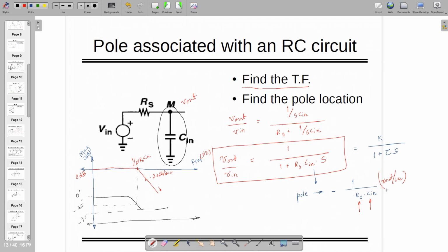So you will have one pole. And if you want to find out the one pole, you need to find out the available resistance seen in shunt with this one. Or you can say that let's change this capacitor with a known Thevenin potential and find out the equivalent Thevenin current, divide it and find out the equivalent Thevenin resistance.